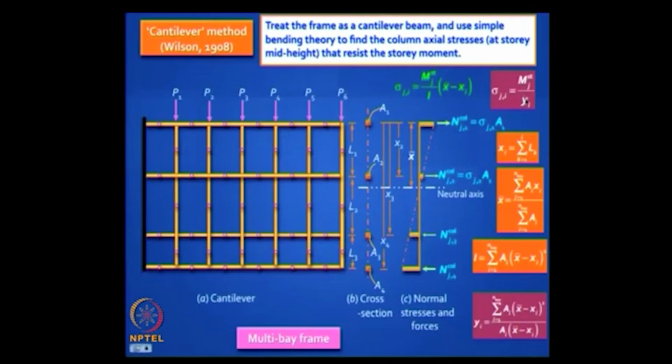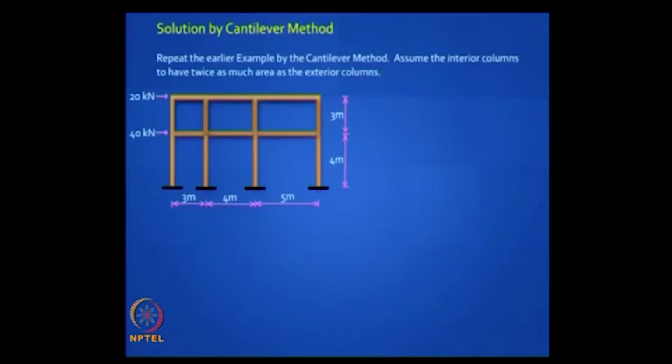It's like let us say you replace that complicated frame with just one top chord and one bottom chord, and the lever arm is Y, then it is a bending moment divided by Y. So this is an equivalent reduced lever arm Y, which you can prove to be, using these formulas, this quantity. I suggest you go through this carefully, understand these equations, and let us just directly apply it to the same problem so you get a feel for it.